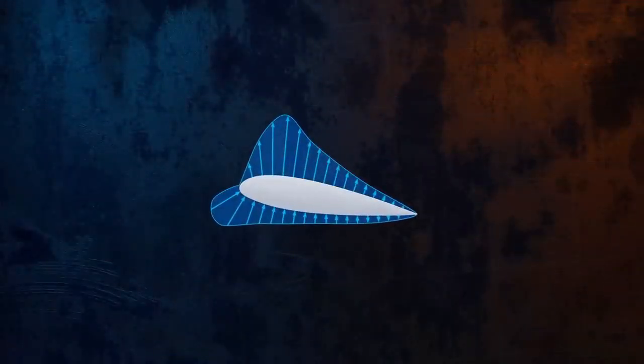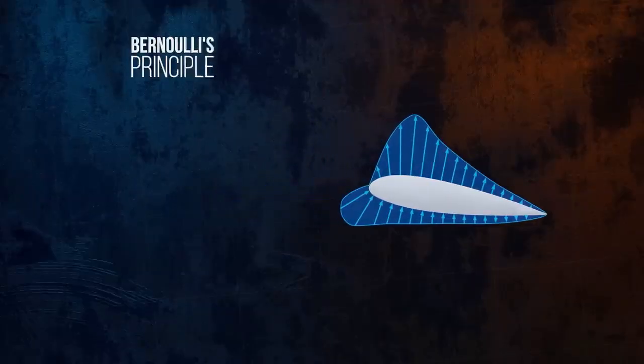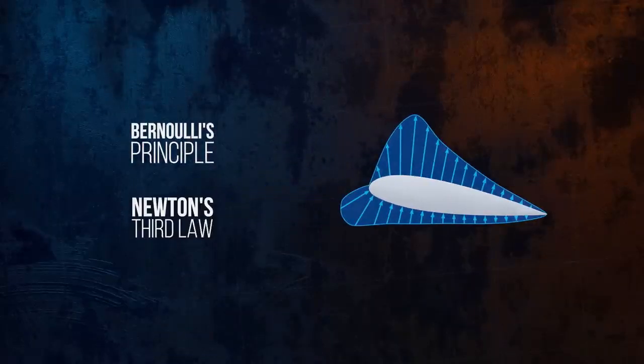The exact cause of this pressure distribution is complex and can be explained in several different ways, which approach the problem from different angles. Explanations based on Bernoulli's principle and on Newton's third law provide valuable insight into how lift is generated, although both approaches have limitations, partly because they're based on cause and effect relationships.